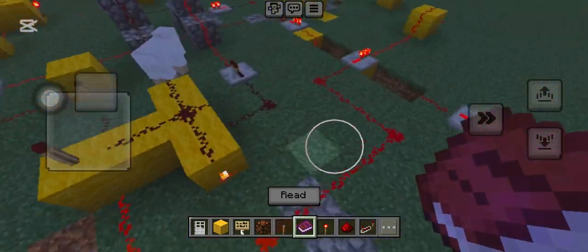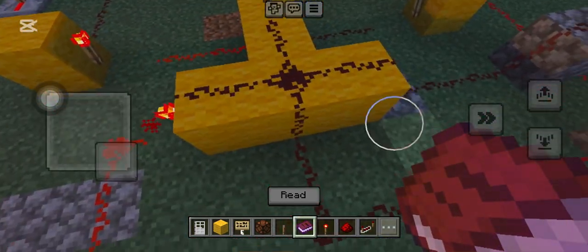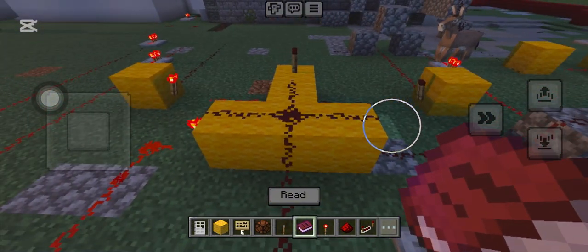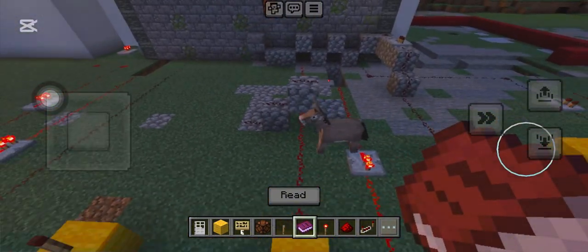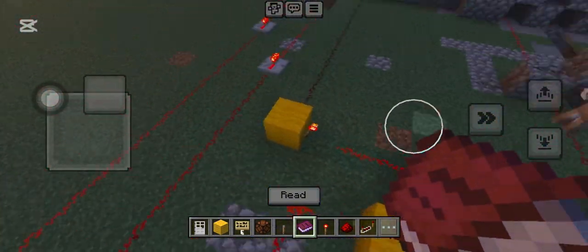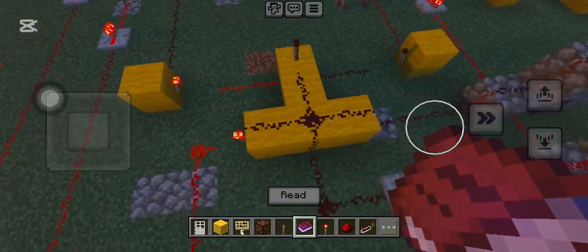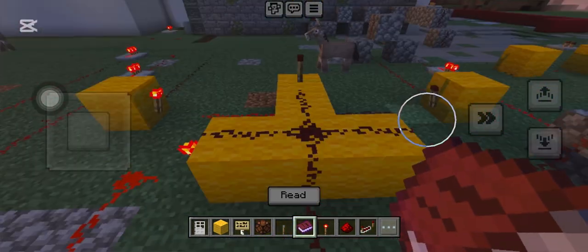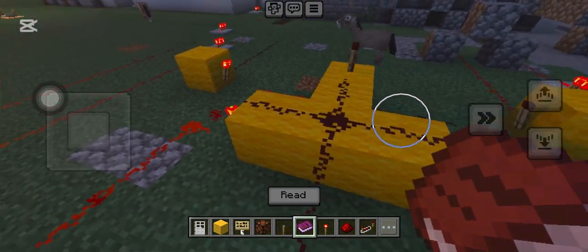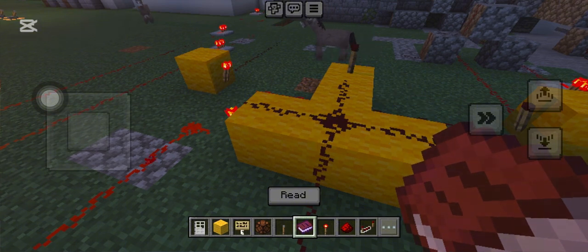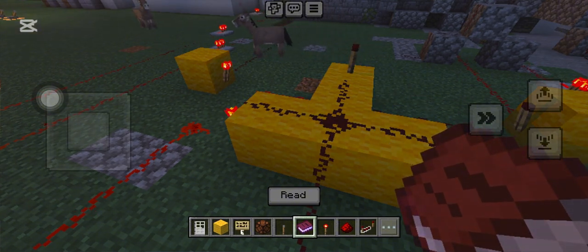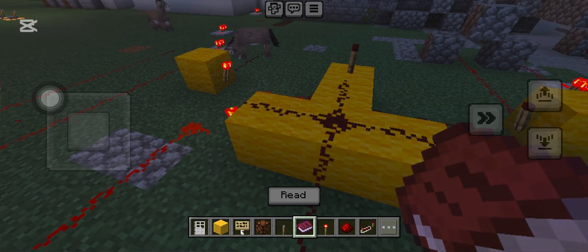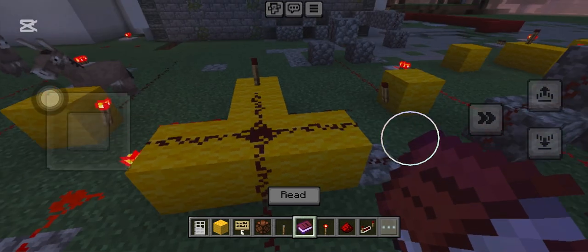The first sum column is to add A1 and B1. And here I have an AND gate, which comes from B1 and A1. In binary adding, 1 plus 1 doesn't just give us 2. Instead, it gives us 10 in binary, which equals 2 in decimal. The 0 is the sum that we write down, and the 1 is for the next column, which we call the carry.